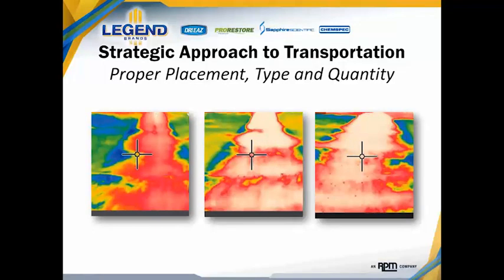But with all of that said, regardless of model or type, again, we learn the same lesson here. It's extremely critical to ensure that we're maximizing the contact of air with the wet surfaces where drying needs to occur. And anywhere that the air movement doesn't exist, and that weakness exists with all of the images that we've seen, anywhere there is not airflow, we're not going to have the drying performance.